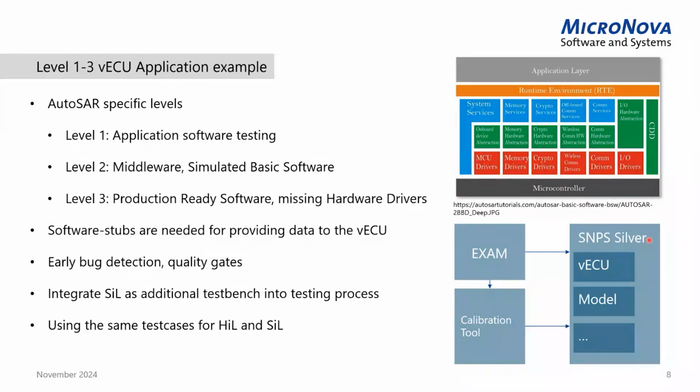We can employ this setup in the development or even testing process. We can create quality gates testing the software before we are even moving to the hardware-in-the-loop simulator. And therefore, we integrate the software-in-the-loop test bench as an additional test bench into our testing process, like previously mentioned.